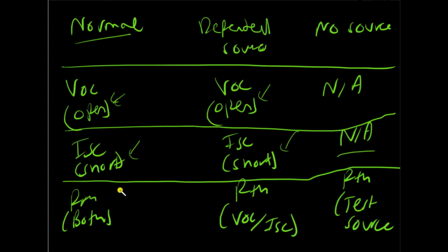For R Thevenin in a normal circuit with only independent sources and no dependent source, we can use both methods that we have studied: one with VOC and ISC, and one where I just remove all the sources. But if there are dependent sources involved, to find R Thevenin, I can only use VOC divided by ISC. And if there is no independent source, I would have to use the test source method that I just described in this video. So these are the methods to find the Thevenin or the Norton equivalent of a circuit, and we've already seen how they are really helpful in analyzing a circuit's effect on a single component. I hope that these examples have made things even more clear.